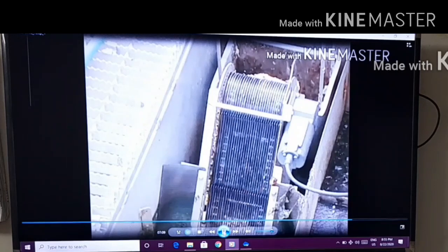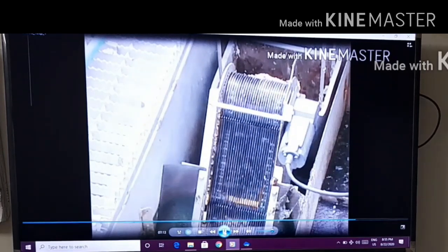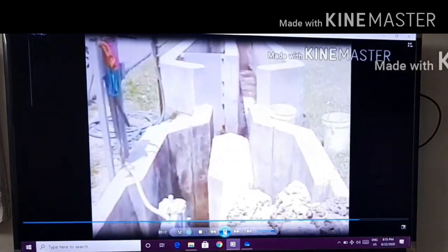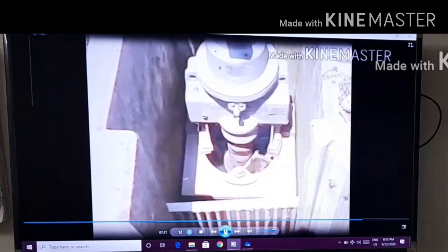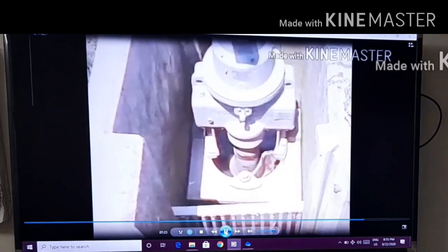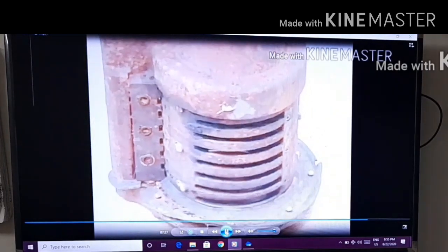The debris removed from the bar screen needs to be dealt with in accordance with the appropriate solid waste regulations. Screenings should not be allowed to accumulate at the wastewater treatment facility, as they will cause problems. In addition to, or in place of a bar screen, a facility may have a comminutor. A comminutor is a device that is designed to shred the materials in the wastewater in order to then pass through a 1/4 inch screen.